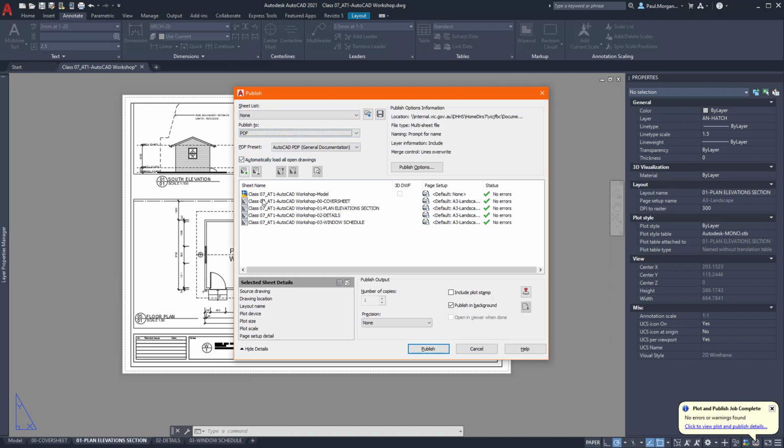The next thing you're going to get is every view and every sheet in the CAD that is open in CAD at the moment. You must remember that it's not just going to have this file, but any file that's open. So if I had another file open up here, like some blocks or a random CAD file, it's going to show in here. So I need to make sure that my sheets are taken care of. And that's why I'm looking at here. You see, it even tries to plot the actual CAD file itself, which is rarely useful.